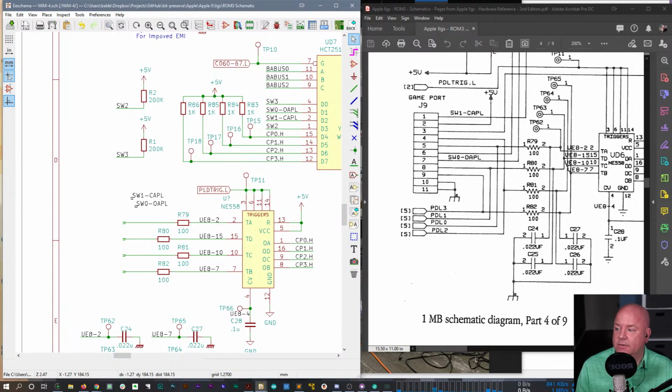Yeah, so just to fill in the blanks, and I'm sure Geek Boy can help out with a little more detail in the chat, just a real quick heads up. Right now everything we have is based on Python. What you saw on screen is basically HTML and JavaScript, a little bit of CSS. But the back end is all Python, and we're using a module called Bleak, which is really nice because Bleak provides a BLE interface on Linux, Windows, and Mac. I have been able to test this meter with at least one Windows 10 machine, two Macintoshes running various versions of Mac OS, and Linux on a Raspberry Pi. Linux on the Raspberry Pi and the Mac work super easy with these meters because Linux, BlueZ, and all that stuff works well. Windows is a total pain, but the Bleak module makes it much easier and more reliable.